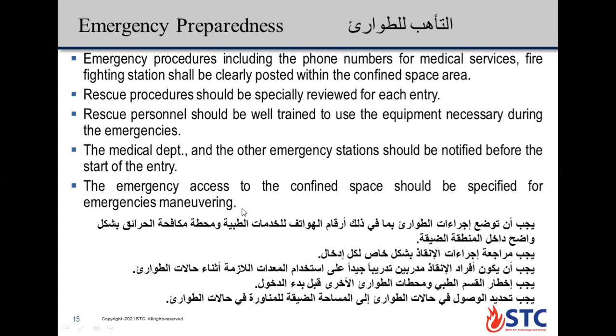The medical department and the other emergency station should be notified before the start of the entry. The emergency access to the confined space should be specified for the emergency maneuvering.